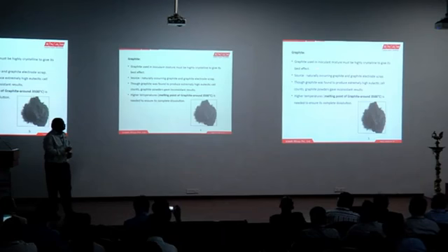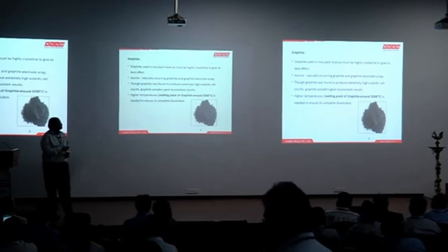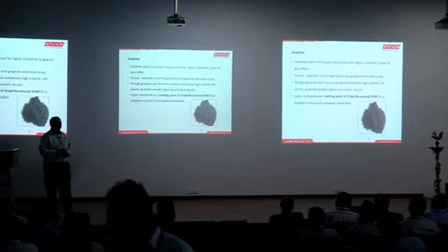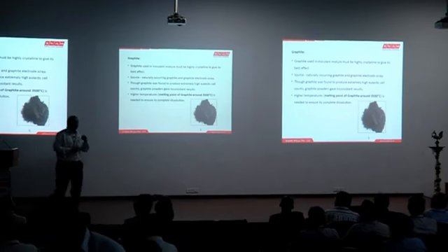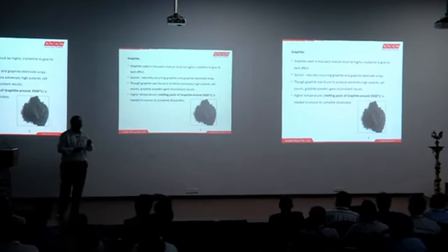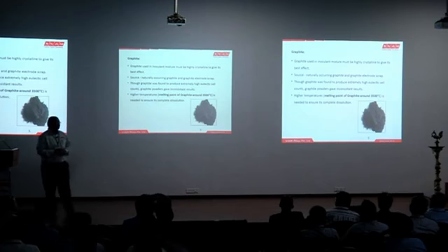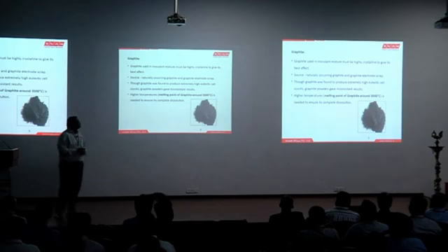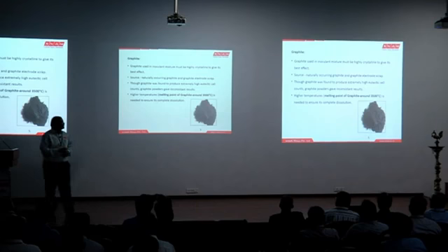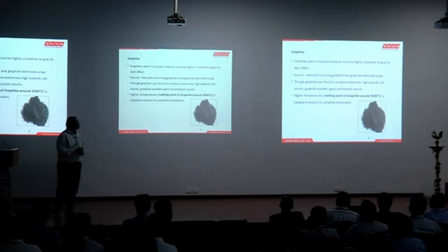Graphite used in an inoculant mixture should generally be highly crystalline in form to give its best effect, because crystalline graphite tends to give you better nuclei, which is going to give you graphite nucleation. But what we have today is crystalline graphite availability and expensiveness coming into the picture. The source of crystalline graphite is generally naturally occurring graphite and graphite electrode scrap, which is generally non-uniform in its properties.